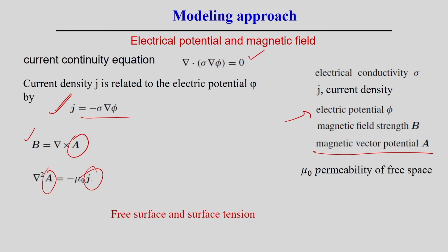If you solve it, we will be getting all this phenomena. Apart from this, we can get the magnetic field distribution also, but this information is also necessary to solve the governing equations, for example, conservation of mass, momentum, and energy equations. There is a need for input from the magnetic field also. That will help in this particular case to get the pressure, temperature, and the velocity field.